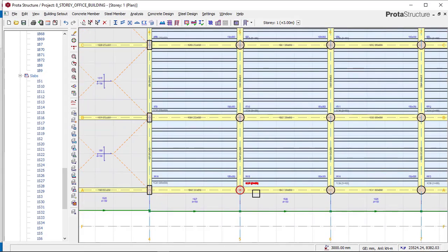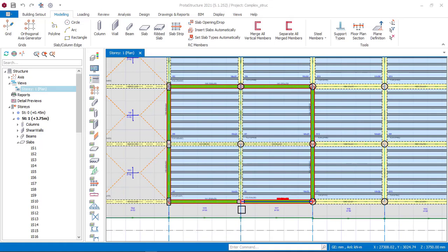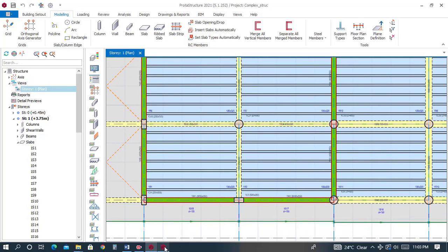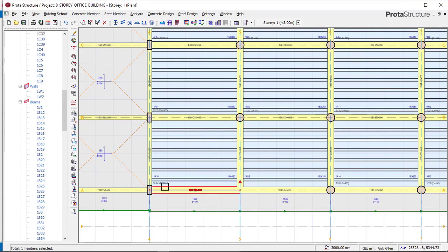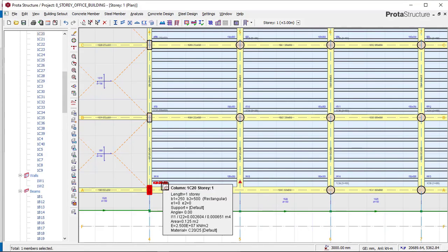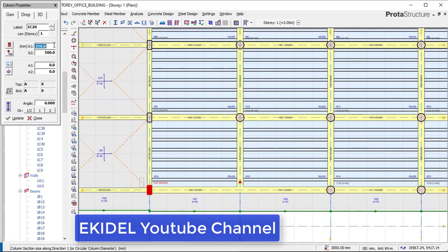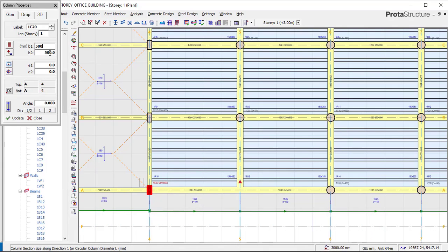Also, if we notice, on this column here, this column is not circular on this plate, on this our sample here. This column here is rectangular and it's being bent in this other direction. So we have to change this column to a rectangular column. So just take these properties, right click and take property of this. But this time it is not rotated vertically, it's rotated on the other rotation. So change it to 500 by 250, and then we input this.